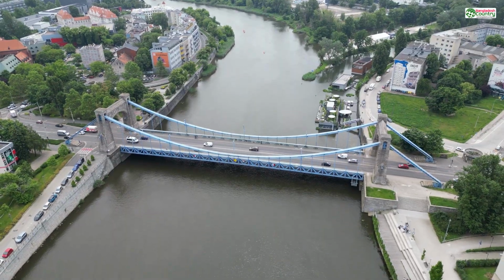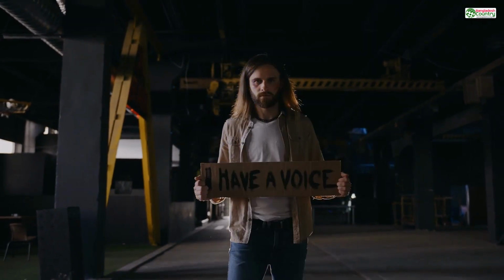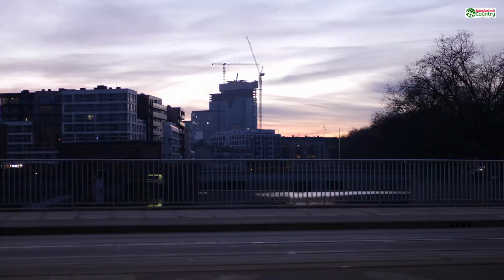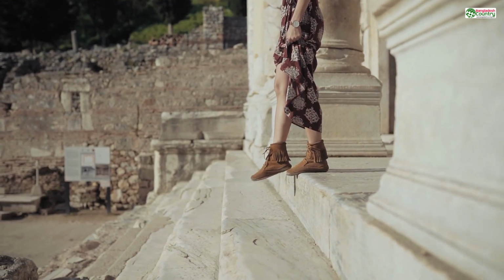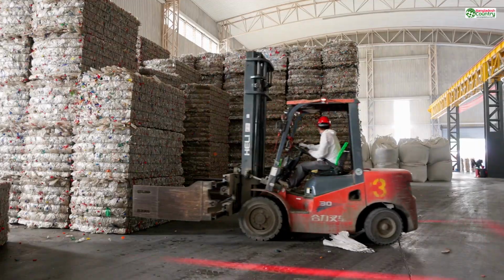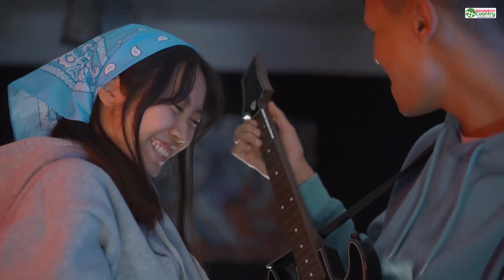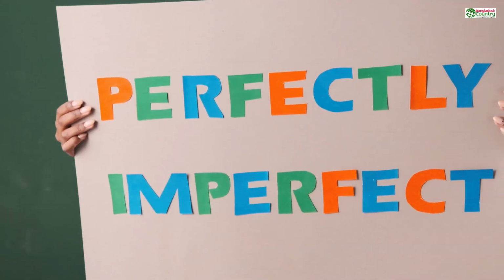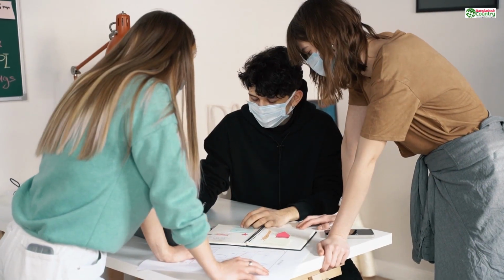But most isn't all. To get it right, you have to do a tiny bit of research on the service's website. This is the single most important habit to develop. Let's walk through it. Go to any online 3D printing service. Find their materials page. Click on the material you're interested in. Let's say it's called versatile plastic or P12 nylon, which are very common. On that materials page, there will be a link or a tab that says Design Guidelines or Technical Specifications. Click it. This page is your Bible.